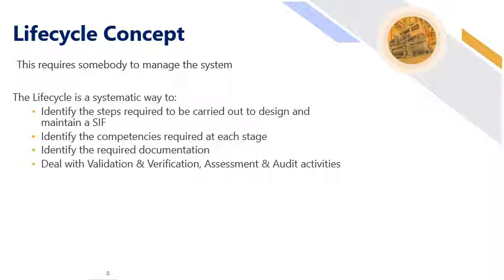Verification is done on the HAZOP and risk assessment, and is a check to see that the process has been done properly and completely as per company standards. Functional safety assessment looks through the detailed design, checks that verifications have been done, and confirms that the design is going to work to the specification, and also goes through the commissioning and testing of the function and signs off that all the processes have been done correctly there.